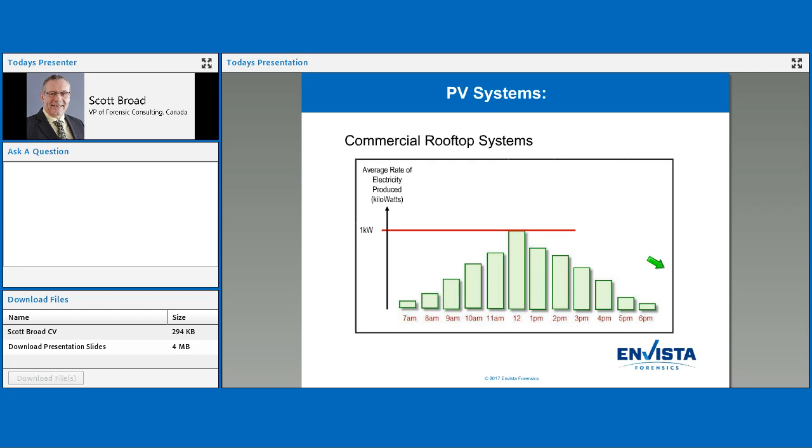What if I were to increase the number of modules I had so that I would start to generate more power in the morning? So, for example, let's just say for a moment that one panel generates 250 watts of output power. We're going to talk about basic electricity in a minute. If we had 4 panels, we would generate 1 kilowatt at its high peak time when the sun strikes it the hardest. So what would happen if we put 5 panels in there? We're going to generate 1.25 kilowatts at our peak power.